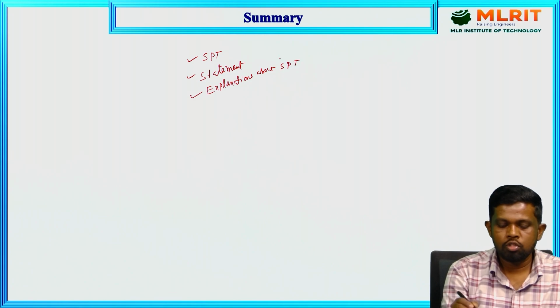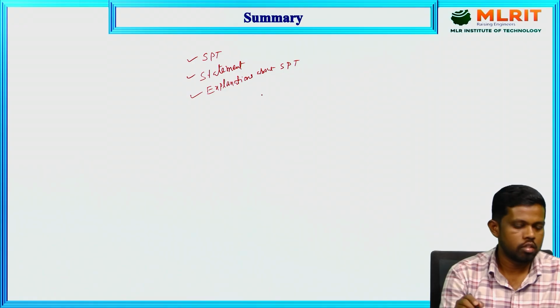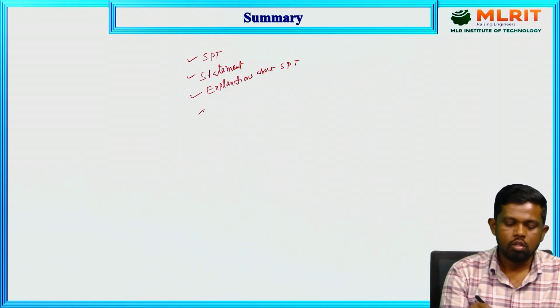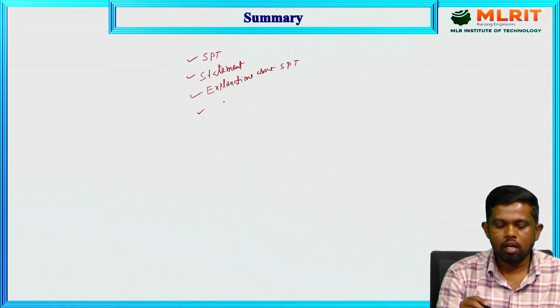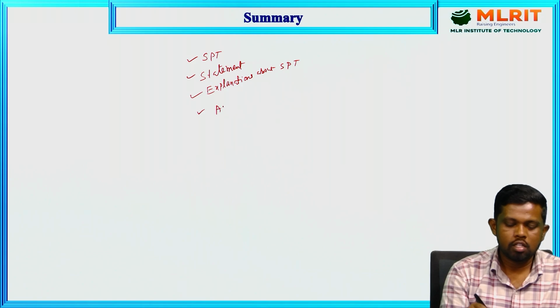First we take a simple network having two or more independent sources. If it is a two-source network, we connect one source acting alone, and the rest of the sources are disconnected and replaced by their internal resistances. Then we get the whole response of each and every element, which we covered in the earlier slide. After this, we need to discuss the applications of the superposition theorem.